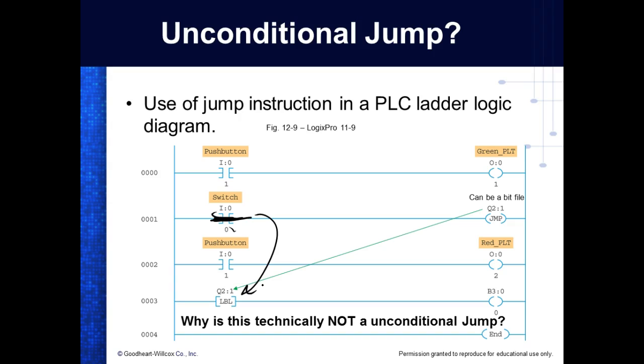So what we have to do is come up here and use one of our internal relays. And we got a ton of them, right? Especially with the 1000s and stuff like that, we got a ton of internal relays. We can't have an input instruction on the left. Now I can have an output instruction without an input instruction, but I cannot have an input instruction without an output instruction. But what we do is we don't sacrifice one of our true outputs, because it would be silly anyway. So we use an internal output.